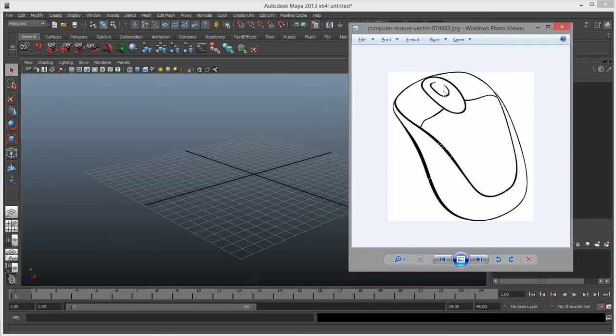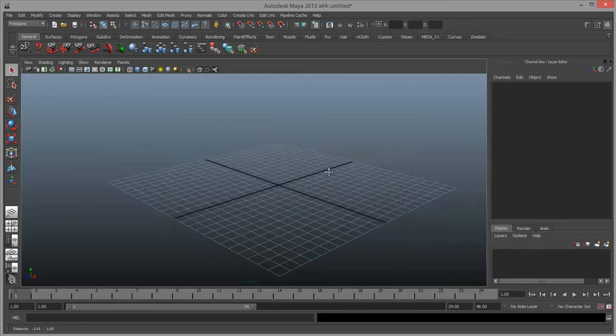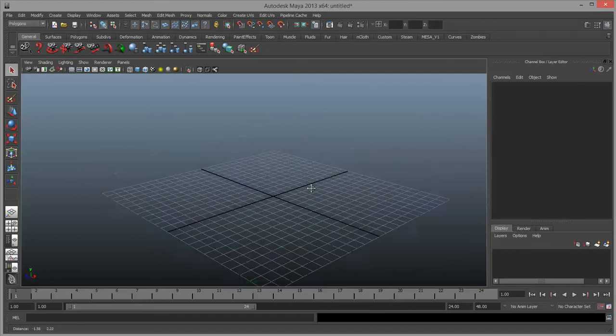You may or may not have a 3rd-button mouse, but it is important for Maya that you have a 3-button mouse. With a scroll wheel, typically you push down and hold the scroll wheel to enact the 3rd button on the mouse. So an example using that in Maya, if I click and hold along with a hotkey, I'm able to slide the view around.